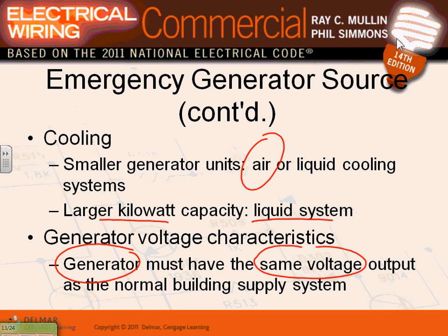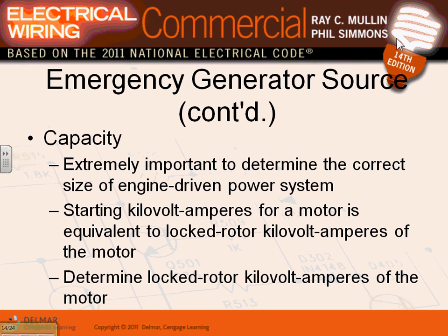Any question, guys? Any question about these, the cooling system for the generator and so forth? Capacity. When we size the generator, guys, we talked about two things: starting capability, the starting KVA of the generator for motors, to determine the correct size for the system starting, and to determine locked rotor current in amps.